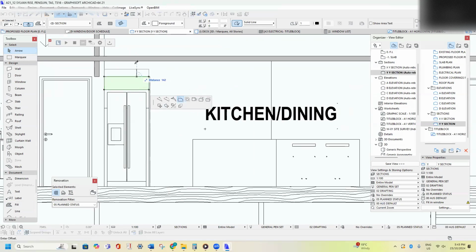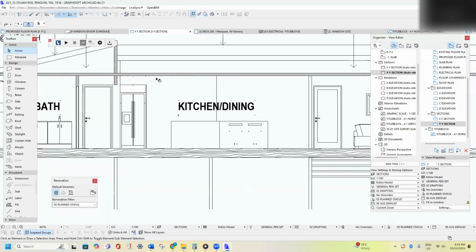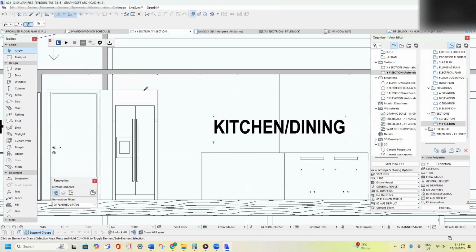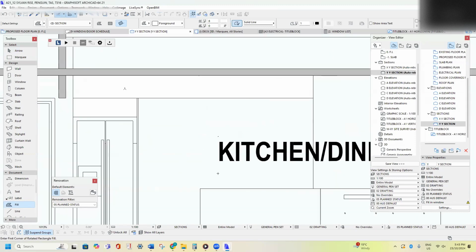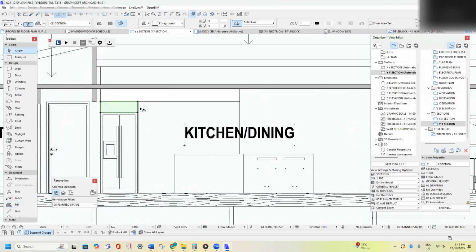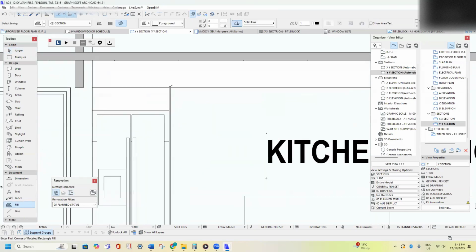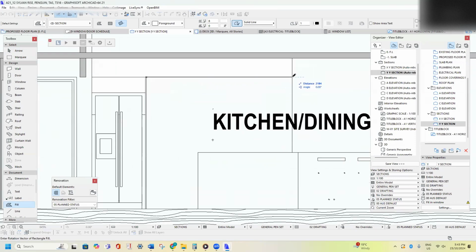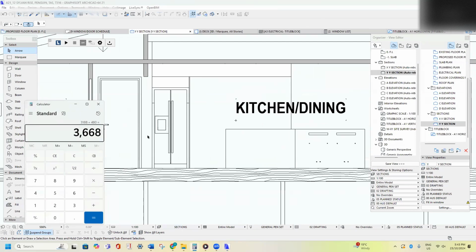And if you click that option, I'm just having to think about this as we draw it. So there'll probably be a 300mm bulkhead over the top, and then the rest of it will be joinery. So if I press Alt on that fill, we can see that there's 2184 there. If you bring your calculator up, press escape, 2184. We divide that by approximately 5 doors, about 436.